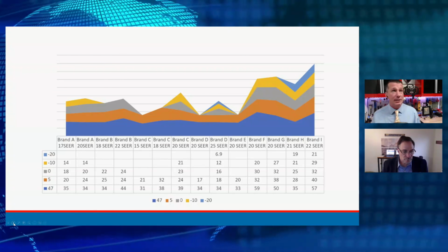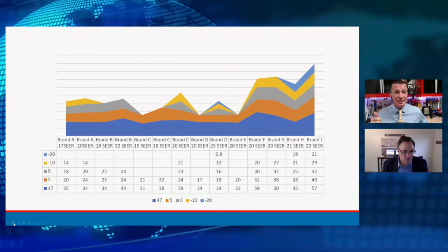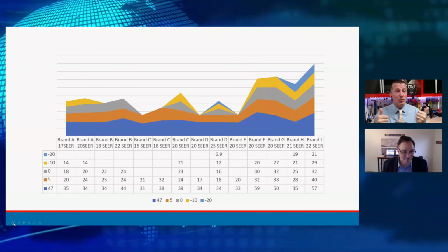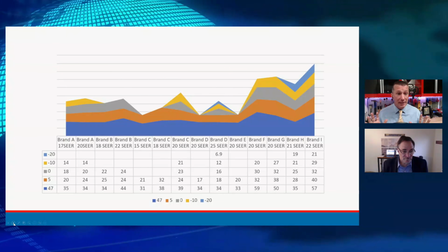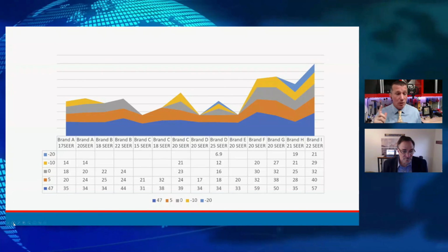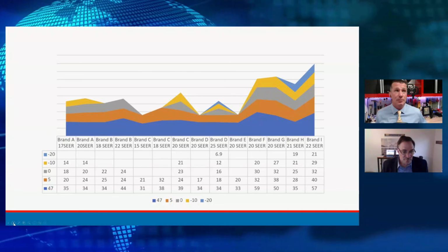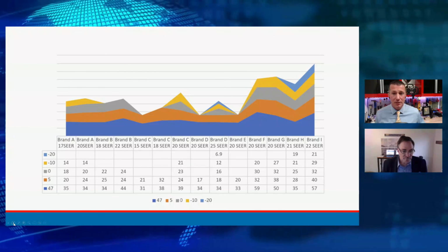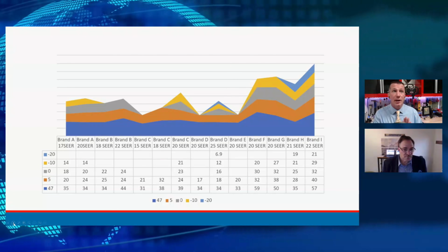If we look right next door, now that is a horizontal ducted system. If we look right next door at that 20 SEER, that is a traditional vertical discharge heat pump, the kind of heat pumps we're used to seeing. But it is an inverter, and it will go down to minus 10, and it also produces 14,000 BTUs at minus 10. So if we start walking our way across, we'll see we're going to go into another brand.